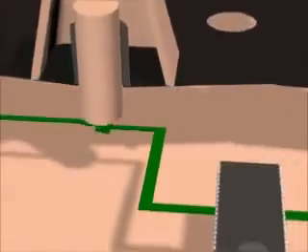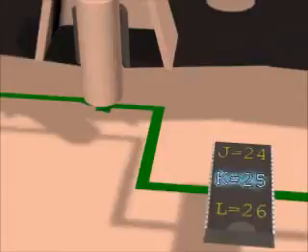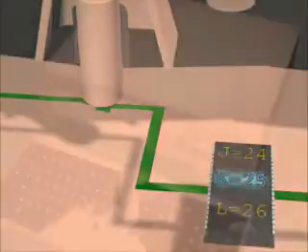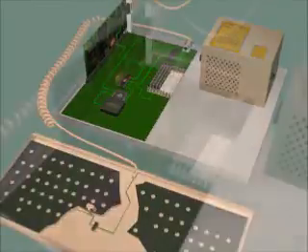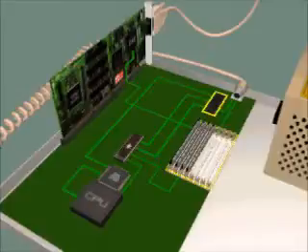How does the computer know which key has been pressed? The current flows from the key to a chip in the keyboard called a microprocessor. This processor matches the keystroke with a table of scan codes. These numbers are used to identify letters in the alphabet. The microprocessor passes this new code number onto a sort of high-tech waiting room in your RAM. That is your random access memory.